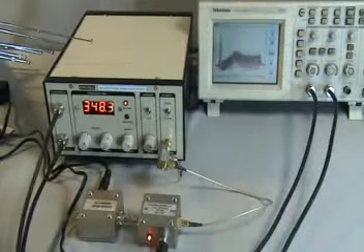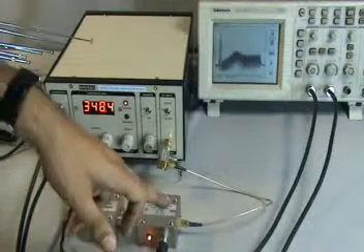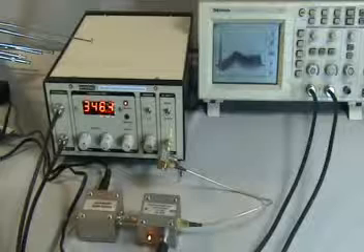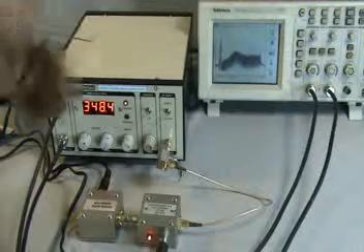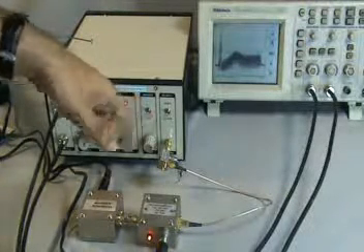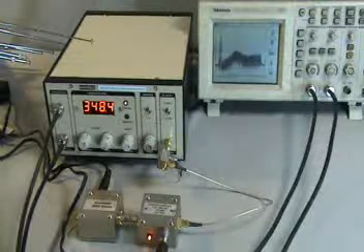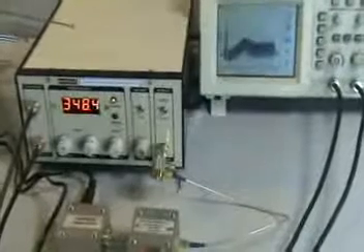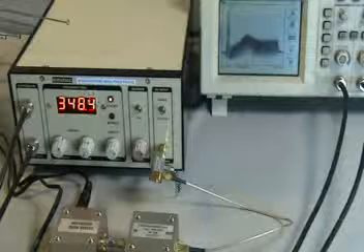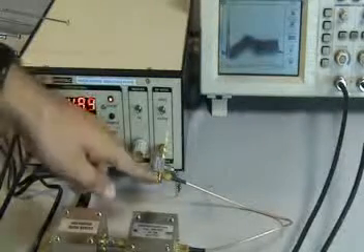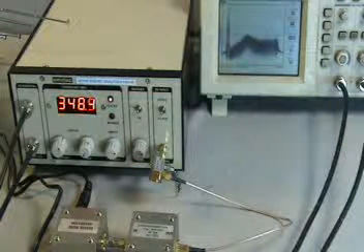In the present setup, we have connected an excess noise generator to the input of the preamplifier, and the output of the preamplifier has been connected to the coupled port of the noise injector cum impedance analyzer. The other port of the injector has been terminated into 50 ohms, and the output port has been connected to the noise figure analyzer. Now we observe on the display that the display looks like this, and this particular port, the input port of the noise injector, is now the test port for us.